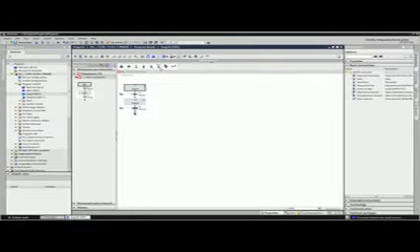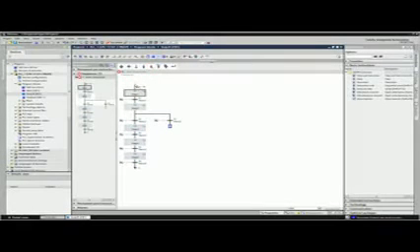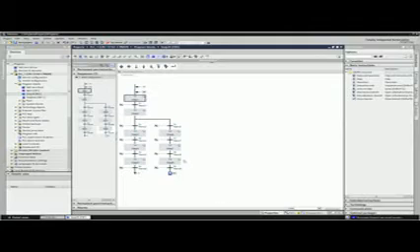Based on the flowchart, you establish the structure of your sequence chain here. You add the program elements into the function block by clicking on the elements in the favorites bar, for example, steps, transitions, alternative branches, or jumps. As long as a step has no actions, it is labeled. For better legibility, give own names to the steps and transitions.